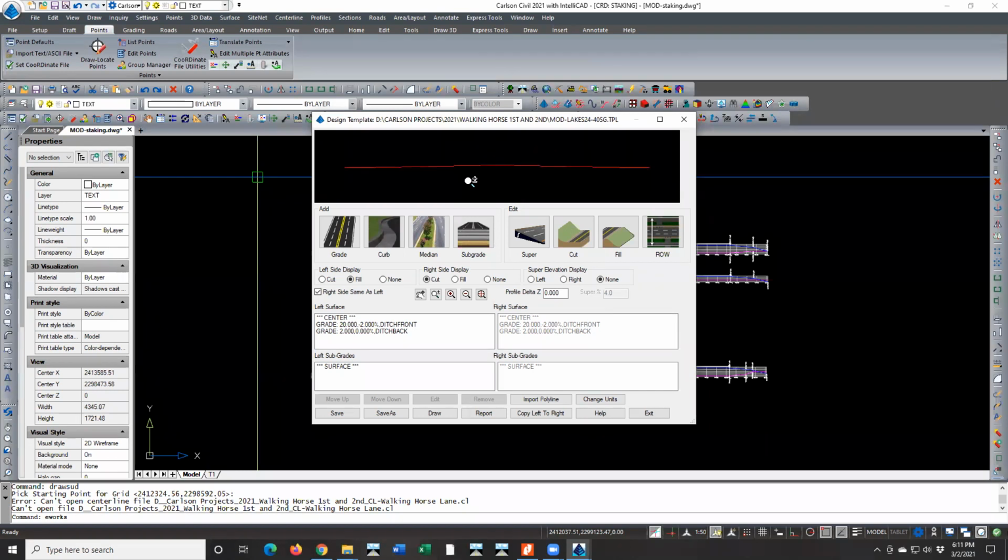And if these widths and slopes change on that top part, may or may not, they're probably just a uniform thickness through there. But sometimes I've seen subgrades go in with flat bottoms and the tops are sloped to match the crown. So just pay attention to whatever's going on there.